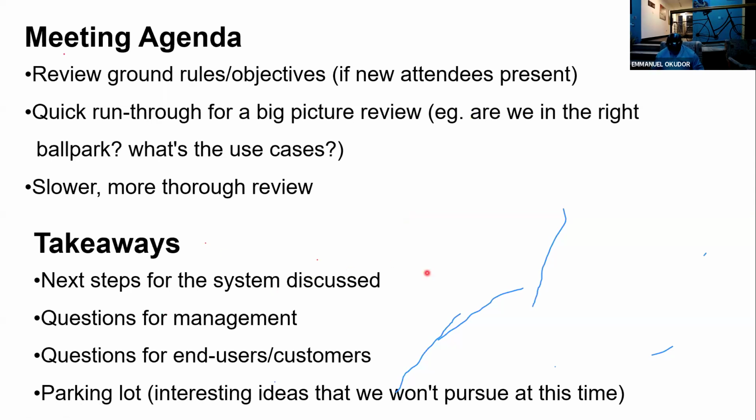Questions for management: there are some takeaways you need to discuss with management because they involve cost. For example, I handled a PHA in Dubai, and one of the recommendations I made was to have 2 out of 3 voting for their transmitters. That is more efficient, and that is the best practice in the industry.